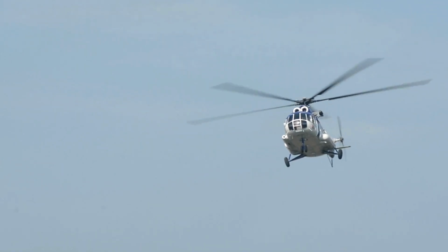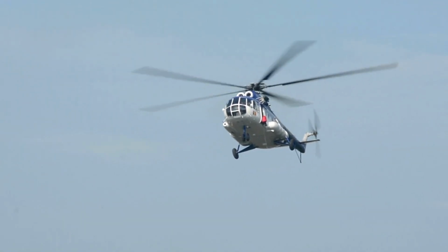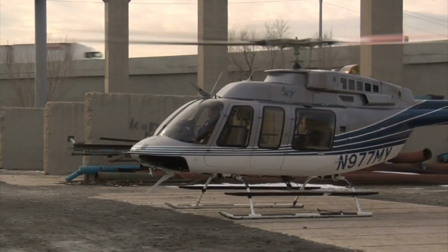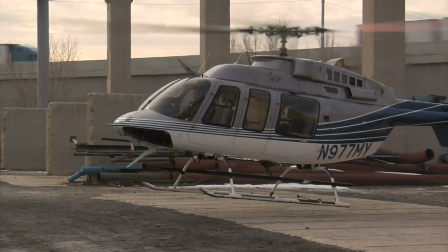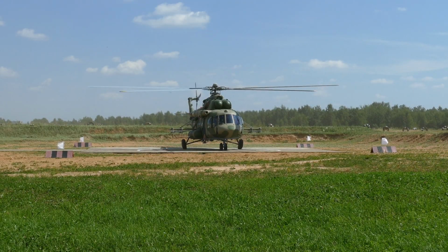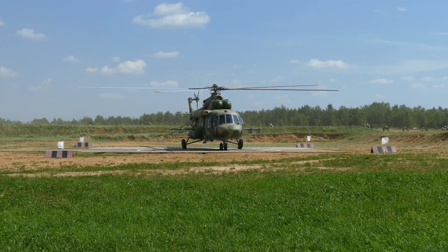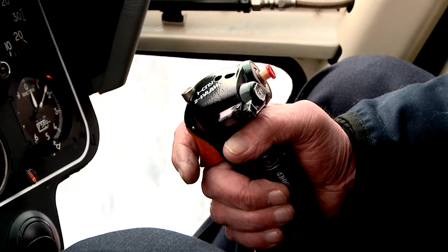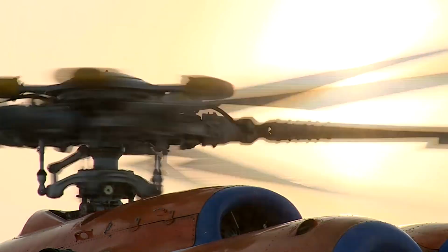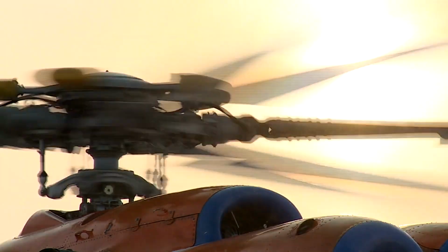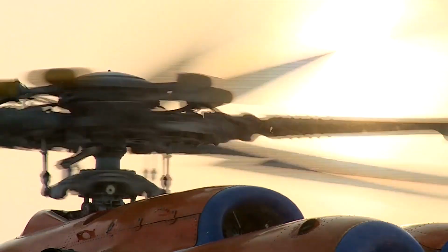Now, let's delve into the graceful hovering turn, a maneuver requiring impeccable coordination. Initiate the turn by applying anti-torque pedal pressure toward the desired direction. The cyclic is employed, usually into the wind, to keep the helicopter over the reference point. As the turn progresses, additional pedal pressure compensates for crosswind forces. A judicious blend of cyclic, collective, and throttle ensures a constant altitude, rate of turn, and RPM.